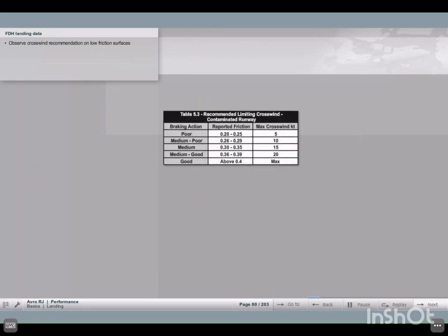It is essential to achieve an accurate touchdown speed and aim to touch down within the first 10% of the runway length. If the touchdown speed is likely to be fast or the touchdown point well down the runway, the approach should be discontinued. Moreover, reduced crosswind limitations should be applied, the same as for the takeoff.